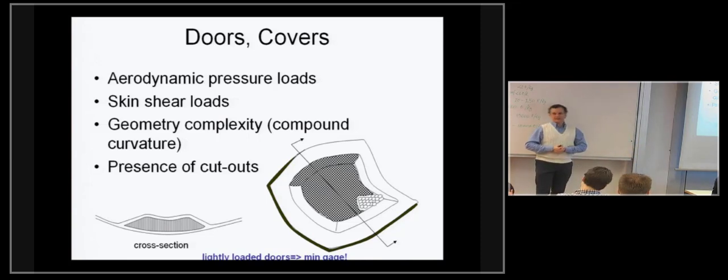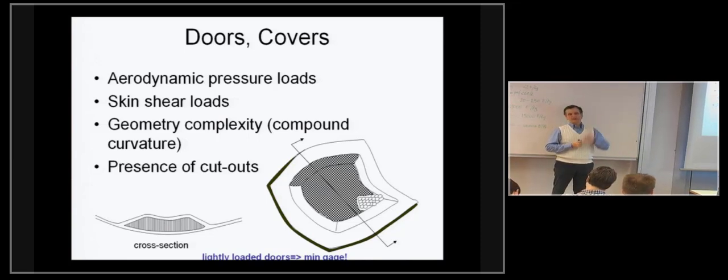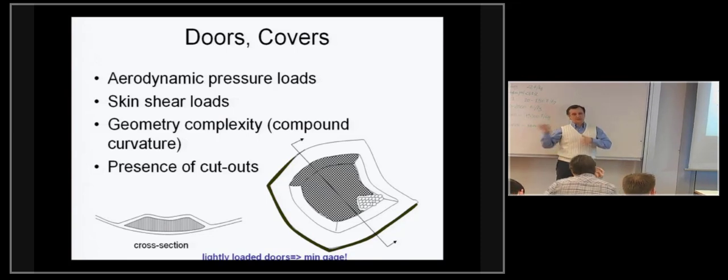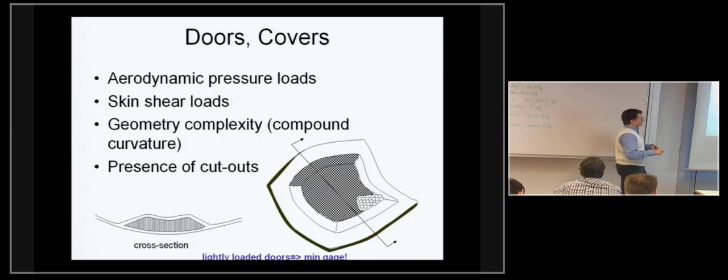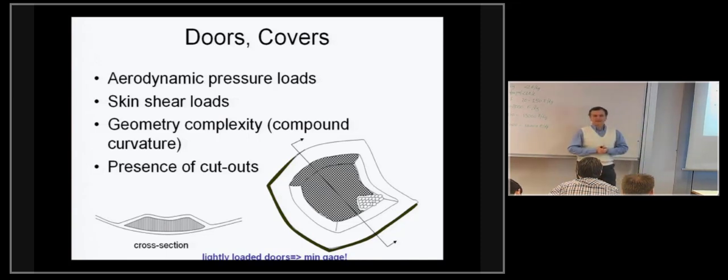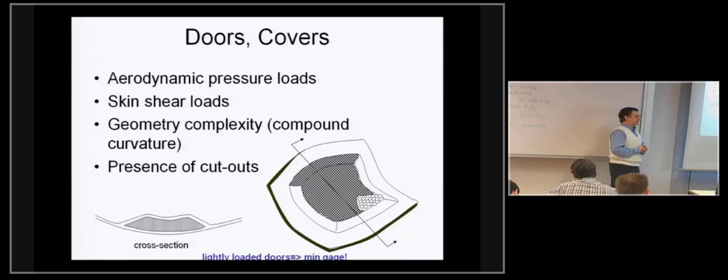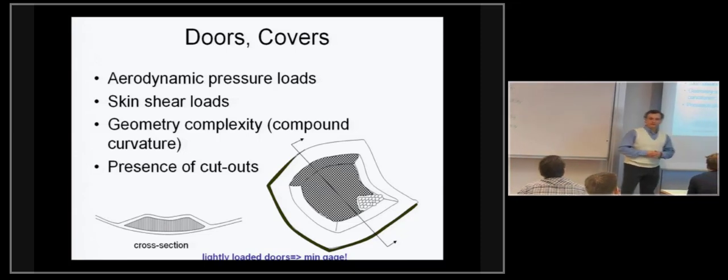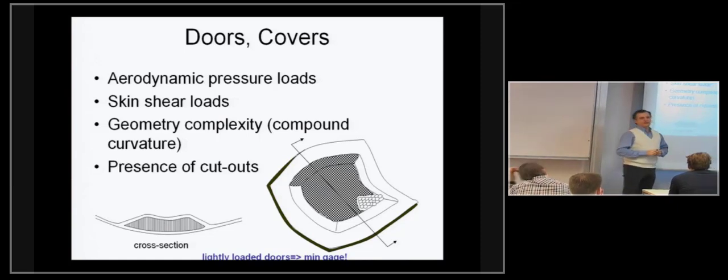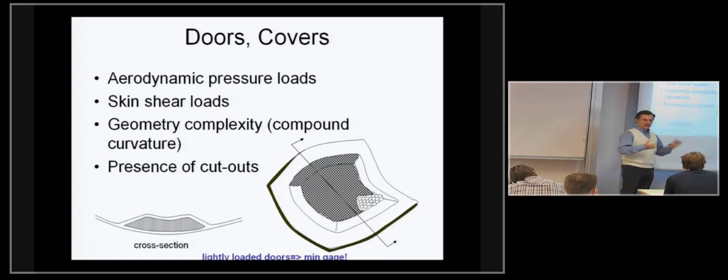Well-known stories on the 737 horizontal stabilizers, which had been flying for decades. At some point, they took some of them off the aircraft and sectioned them, and they found kilograms worth of water that had accumulated over the years, which had completely destroyed the core because that was a sandwich structure. But because it was a very conservative design, designed back in the late 70s, early 80s, I guess, it was still flying and performing quite well with minor aeroelasticity concerns because of the mass having changed, but it was nothing that the pilots couldn't deal with.